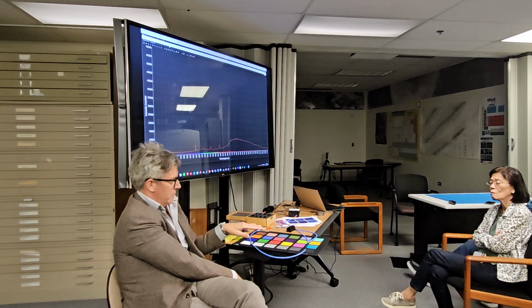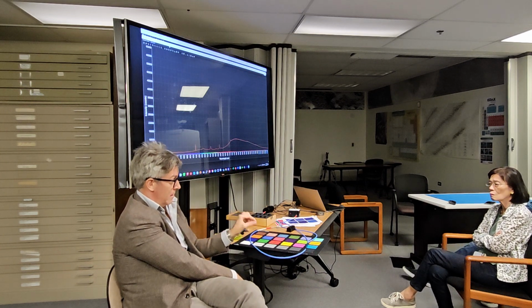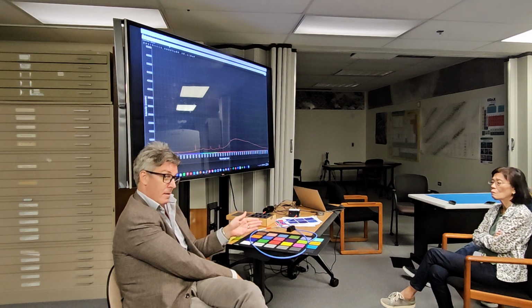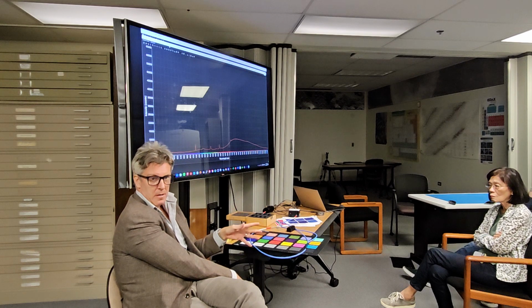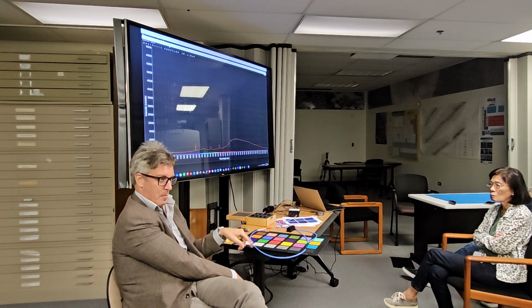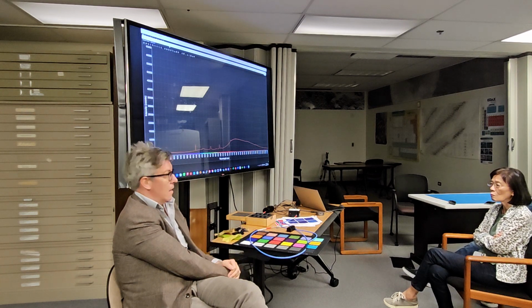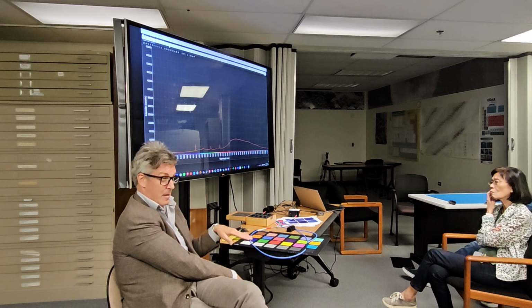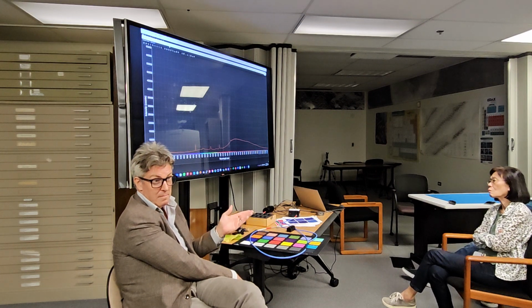say we have our photosensitive material, photons, photoelectrons beneath each one. In a CMOS detector, we have a bucket and a gate. We open the gate for the integration time, right? So while it's open, photoelectrons are filling the bucket capacitor, and the bucket fills. What you just saw is when the bucket gets full and it can no longer take any extra electrons, right?